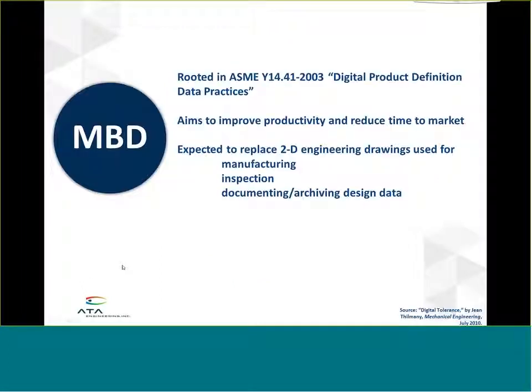The idea of model-based definition goes pretty far back, when people were still making drawings by hand on drafting tables. It was more formally standardized into ASME Y14.41-2003, Digital Product Definition Data Practices, and more recently updated in 2012. ISO and JEITA have MBD standards as well.